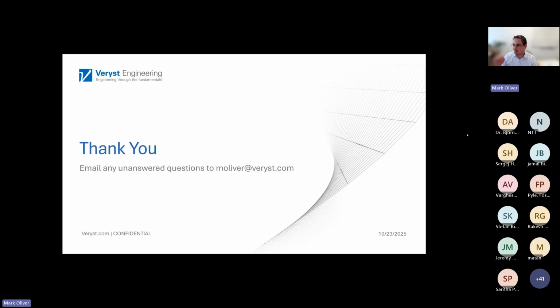All right, here's a question about DMA TTS applicability. If you're doing DMA TTS, you're making some assumptions that you have a rheologically simple material. It depends on how critical the accuracy of your creep data is. An approach that we will often take is to run a DMA test, use TTS, and then get a creep curve.